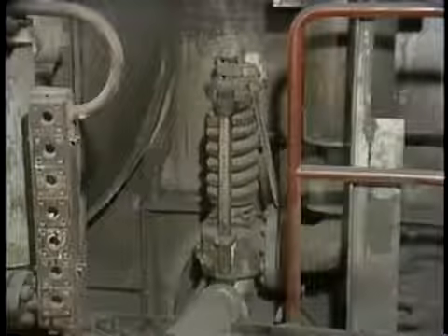To protect superheater and reheater tubes from overpressure and to provide an alternative flow path for steam, safety valves are installed in outlet lines of superheaters and reheaters. If steam flow to the turbine generator is cut off, the resulting increase in pressure will cause the safety valve to lift. This, in turn, will provide a flow path for steam, protecting the tubes from overheating. On drum-type boilers, safety valves are also installed on the steam drum.